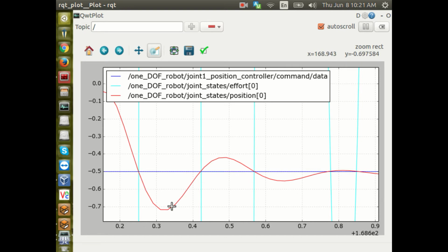This is called overshooting. Then it oscillates back, overshoots a second time, a third time, and about here it begins to get close to that signal. Now this is just using the P controller, no I, no D, so this takes almost a second to become steady, still with some error, right? So this means it's a very slow controller.